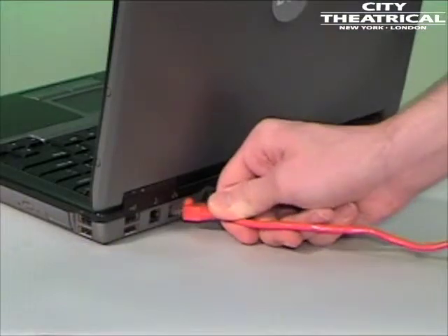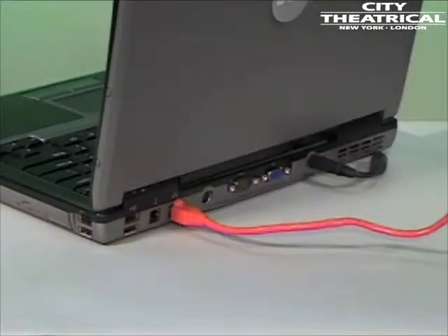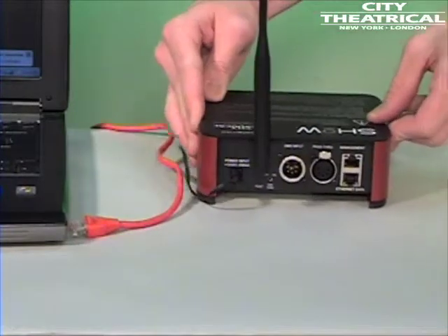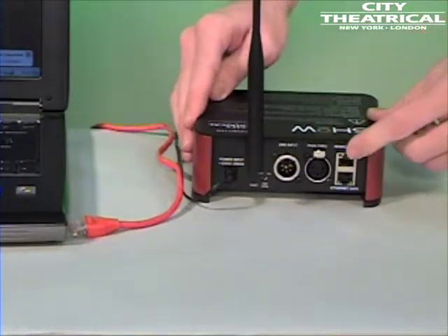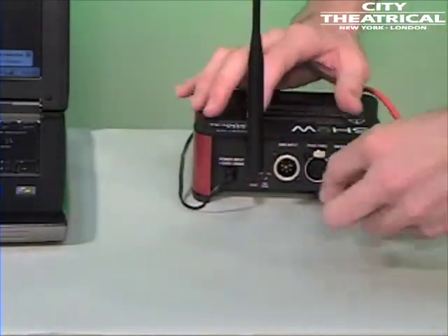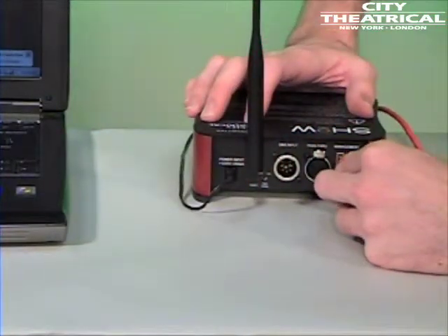The SHoW DMX transmitter has an RDM controller built into it called the SHoW DMX monitor. It can be accessed with a laptop and a crossover RJ45 cable via the management port on the back of the transmitter. The monitor is embedded in the transmitter and accessed using a web browser.